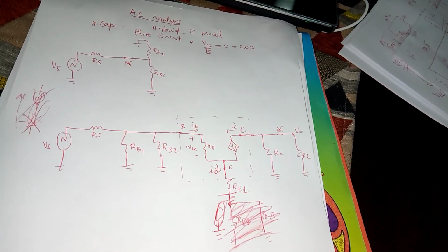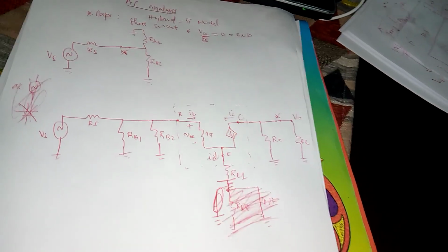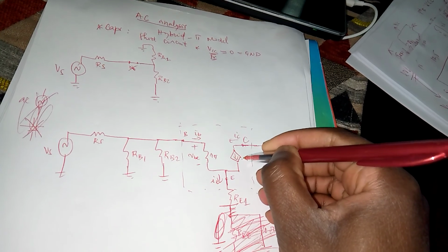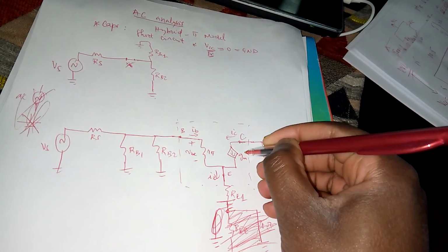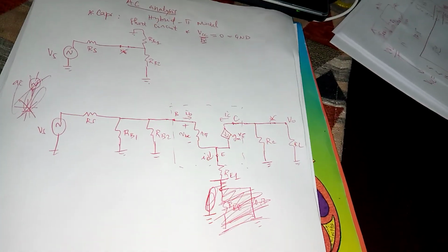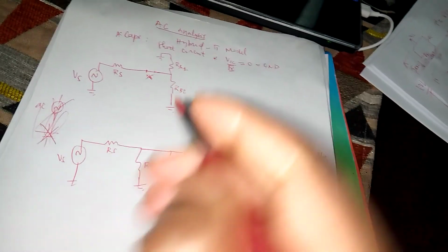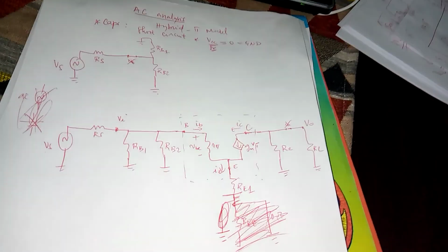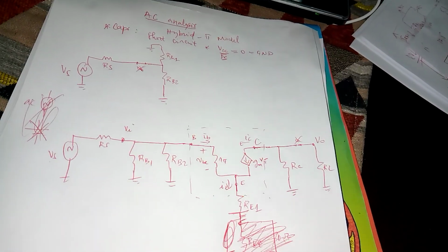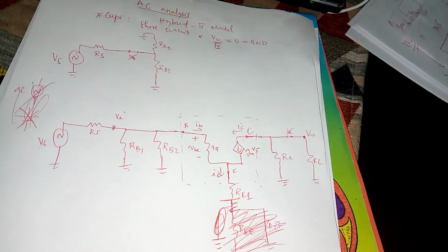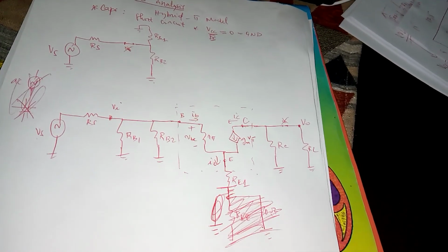But what do you need to complete this? You need to identify the three characteristics of an amplifier. Obviously, IC is also, as we computed it before, gm times V pi. But you need to identify where the input Vi is, because we know VS drops a bit before it becomes Vi. Vi is always the actual signal that at the end of the day gets amplified, and it's a piece of VS. Vout, of course, is the output voltage, in this case because it's common emitter, you're observing from the emitter and it's on the collector.